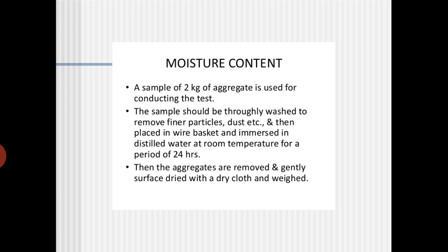If you weigh those particles, how do you take the weight? Initially you take the empty weight of the beaker before filtering. Then after filtration and oven drying, take the final weight of the beaker. Then you will come to know how much the total dissolved solids are. One method of determining total dissolved solids is the conductivity technique, and one more is the oven drying method. Of course, the oven drying method is more accurate than conductivity.